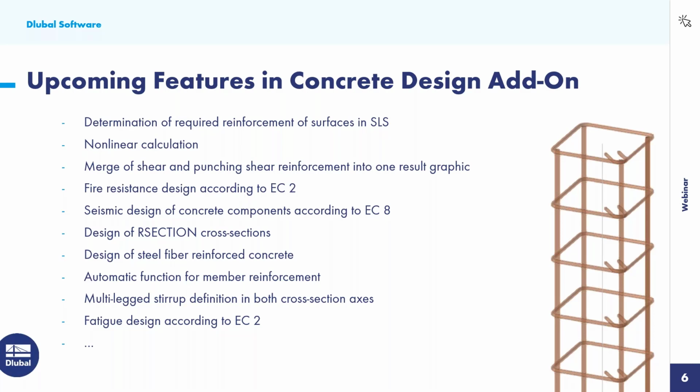Then nonlinear calculation is also in development for ultimate limit state and serviceability limit state for slabs and members or beams. Then one upcoming feature is also the merge of the shear and the punching shear resistance and reinforcement design checks into one graphic. Then, of course, fire resistance design checks, and seismic design of concrete components according to Eurocode 8.